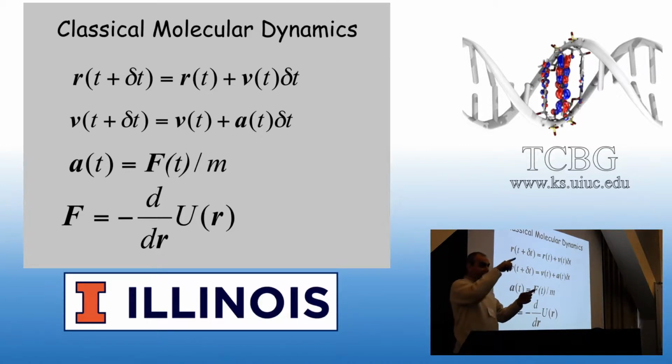In order to be able to describe this period nicely, seeing the up and down and everything, you need to have a few snapshots. If you take just one snapshot, you might see it always in the same place if it matches the frequency. If you take two snapshots, you might end up in the same place too, it comes to zero, back and forth. So you have to take enough snapshots of that periodic behavior to be able to reproduce it.